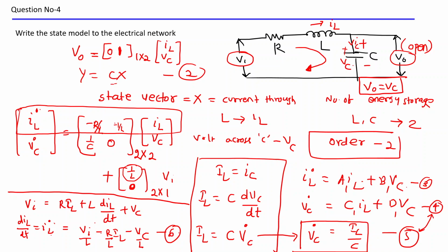Now from different aspects we are building up how we are able to find the state vectors, because our aim is to find the system response. For finding the system response we have to find the transfer function. For finding the transfer function we need to find the ABC coefficient matrices. So from a variety of questions, how you are able to find the ABC matrix is important.